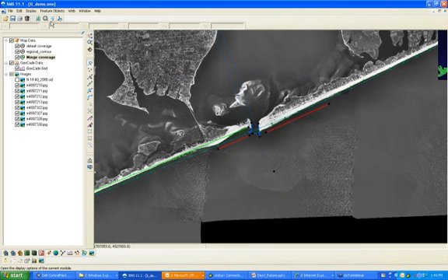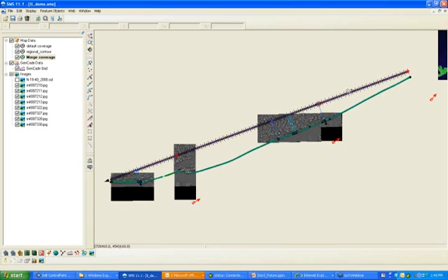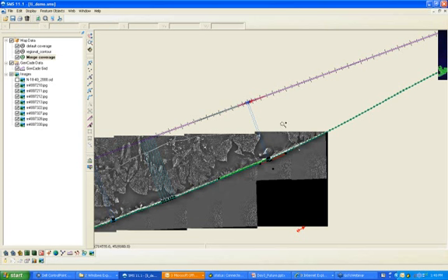So based on the way I've drawn my arc, the seawall is actually not going to look like that based on the cell sizes. So with seawalls and other things like seawalls, you probably will need a smaller cell size. So here, what you can see has happened is we have the smallest cell size at the inlet, and it's grown in both directions from there.